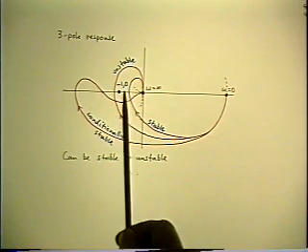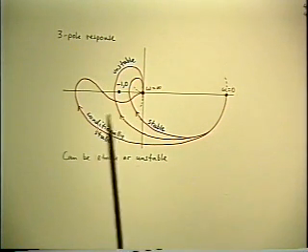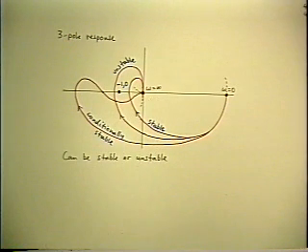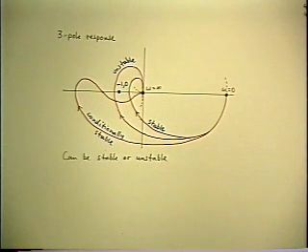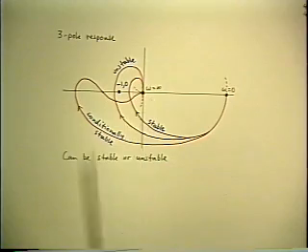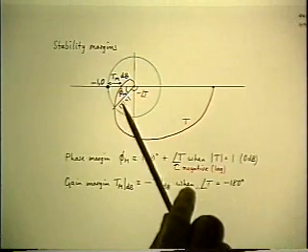So you see, there's all sorts of hazards in a conditionally stable system, mostly to do with abnormal conditions. But to try to anticipate all those possibilities is a pretty tough thing to do. So the basic conclusion is, don't design a conditionally stable system unless you really have to. Stay away from it.